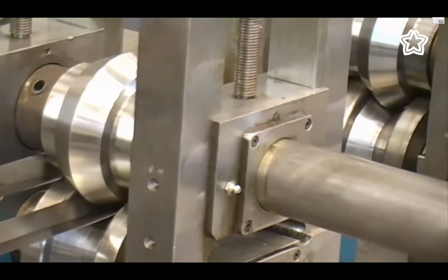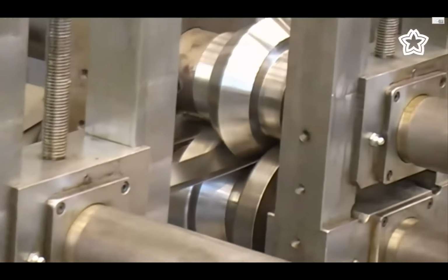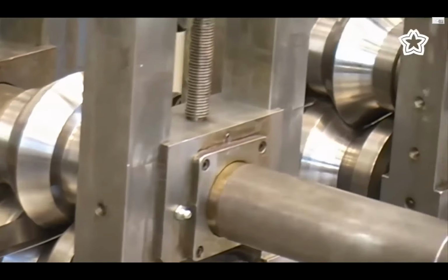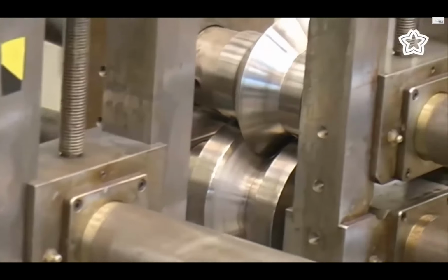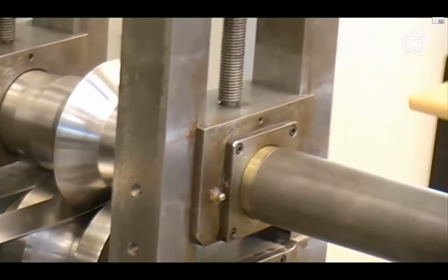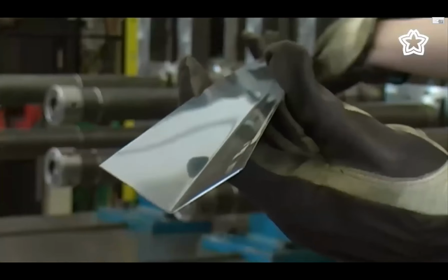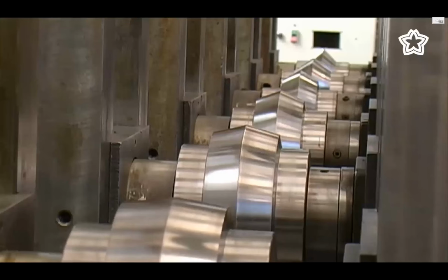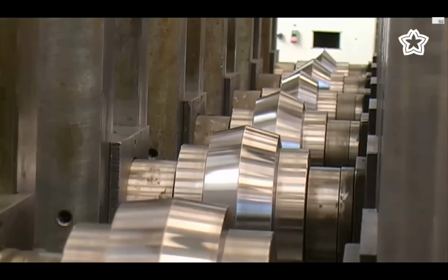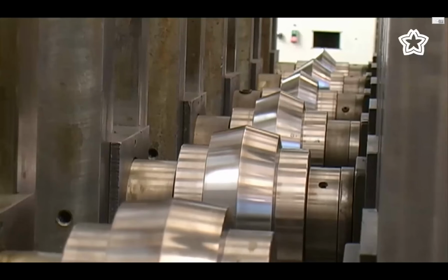Note that the sheet springs back. Spring back is the elastic deformation that appears after shaping. Spring back is compensated for when the roll stands are constructed, thus overbending the sheet and letting it spring back into the correct form. What the roll forming tool looks like is decided by what kind of profile is needed.